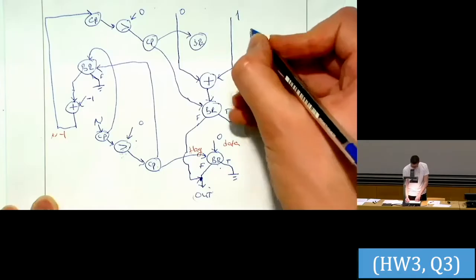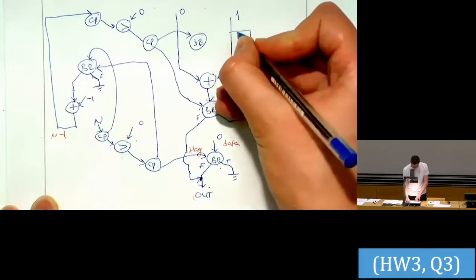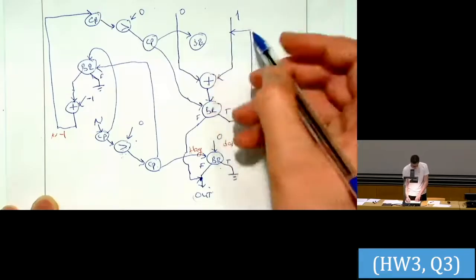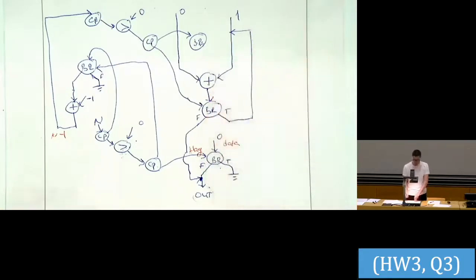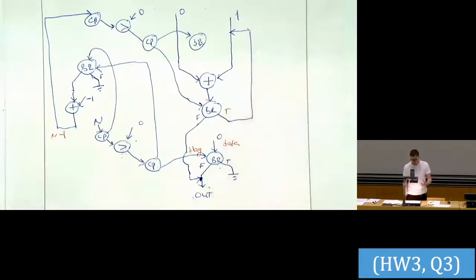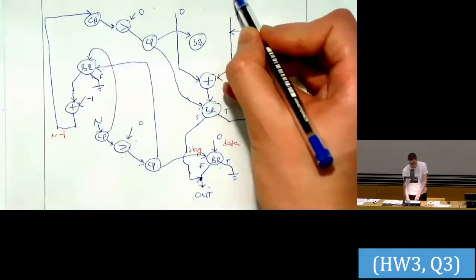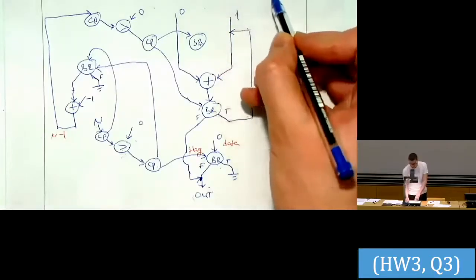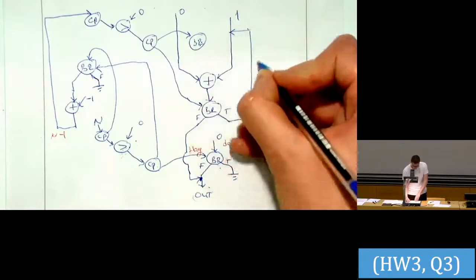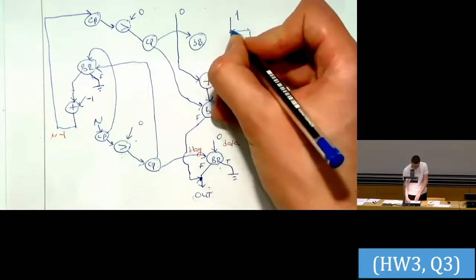So this will need to be connected here. But we'll need to forward the same value to this branch logic 2, because this will be the n minus 2, if you will, right? This data forwarded here is just the result of the previous iteration, n minus 1, but we will also need n minus 2, right? And then we will get it from here. Basically, we will forward this value here and then copy it.